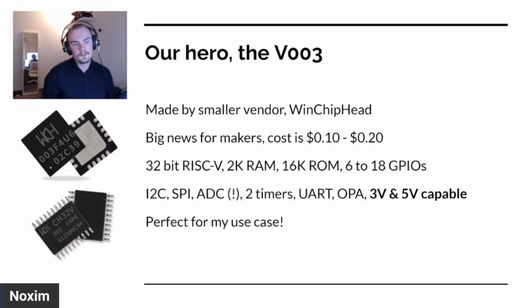But I also wanted to have the option to make a rechargeable lithium polymer battery, and those batteries have a voltage of 4.2 volts at maximum. So because this chip supports anything from 3 to 5 volts, I could use any sort of power source I wanted without any external components.